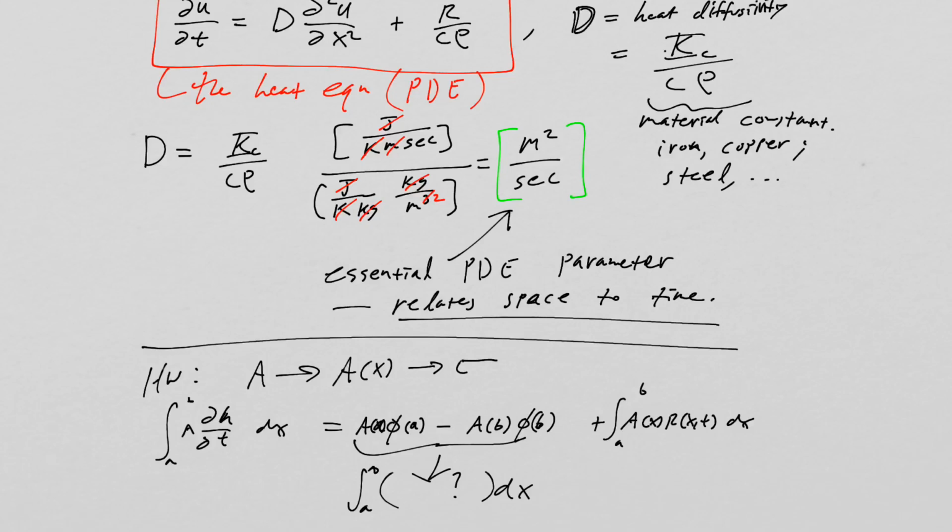So the kind of situation is where basically our metal rod now might have variable cross-section. So it could have A here, but then it could have a bigger cross-section in one part and another. Of course, when you have a bigger cross-section, there should be less resistance to heat traveling through it, so you get greater flux, all things considered.